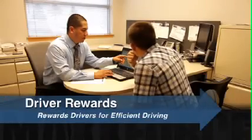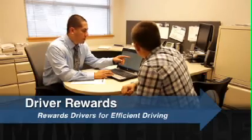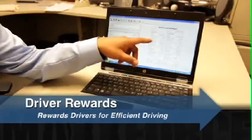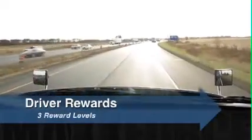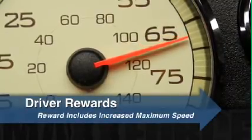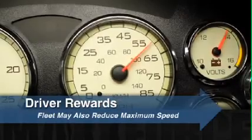The Driver Reward feature is designed to give the operator incentives for driving more efficiently. Driver Reward measures fuel economy and/or the percentage of idle time compared to programmed targets that reward the driver with extra vehicle speed. There are 3 levels of driver achievement that the customer can program: expected, good, and excellent. The reward of increased maximum speed may be applied when a driver meets or exceeds a threshold. A fleet may choose to reduce vehicle speed if minimum goals are not met.